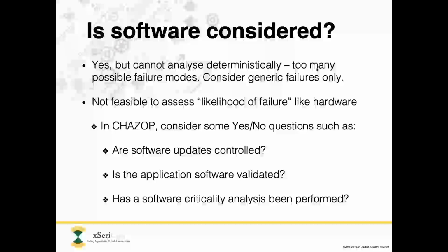But there may be other kinds of safeguards which are provided by other systems. For example, the control system itself may have alarms, such as a watchdog alarm or a communication failure alarm, or whatever it may be.